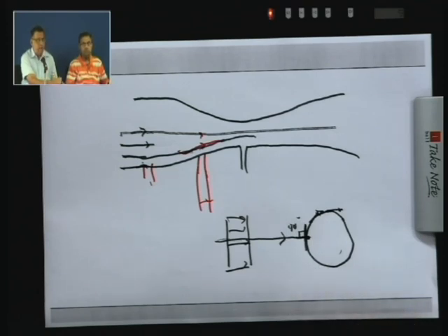Sir, is there any advantage of the Venturi meter over the Pitot tube? Now the Pitot tube you use to measure the velocity, and the Venturi meter you use to find the flow rate directly. Of course, if you have a fully developed flow in a duct, you can traverse the Pitot tube and find the velocity at different points along the section, and in some cases you may be able to carry out an integration using a numerical or graphical method and find the volume flow rate, but then you have to put in that additional effort.